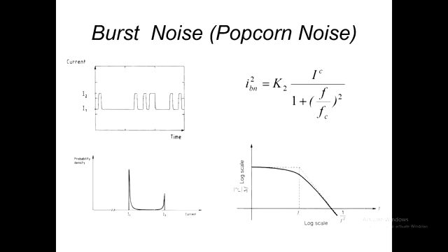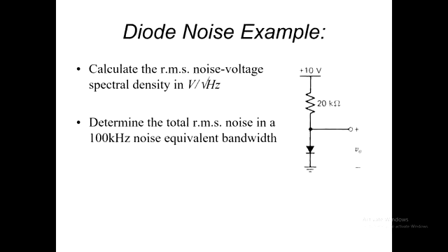I won't bring it in to show you, but because it's only ever so often, you get little pop, pop, pop from one side. But it's jumping between two levels, also called telegraph noise, and you get this two-horned amplitude distribution. That's just a peculiarity we won't worry about. I just put it in there for the sake of completeness.